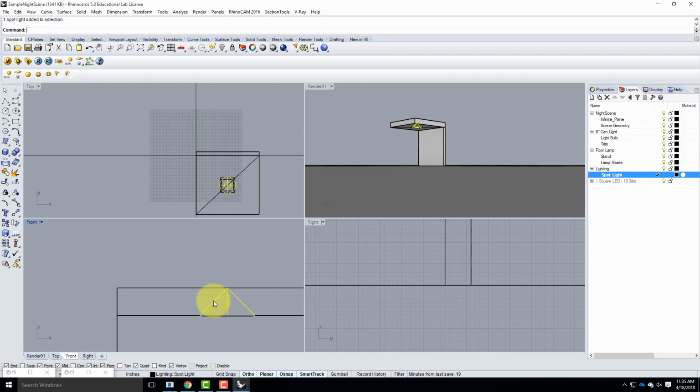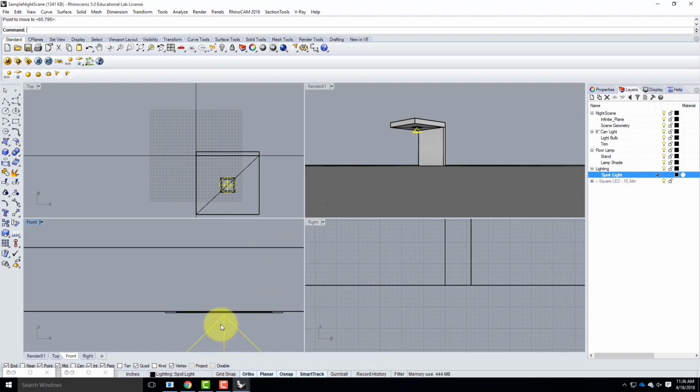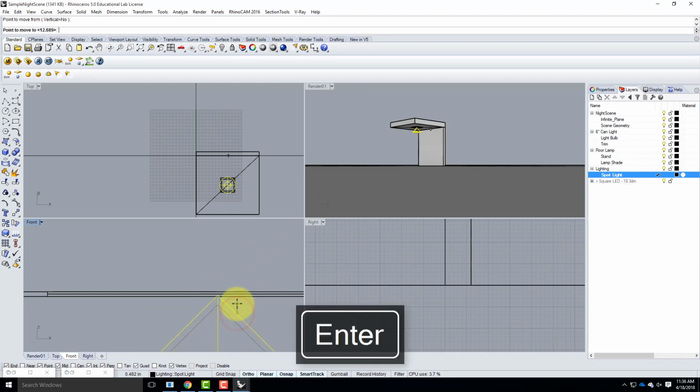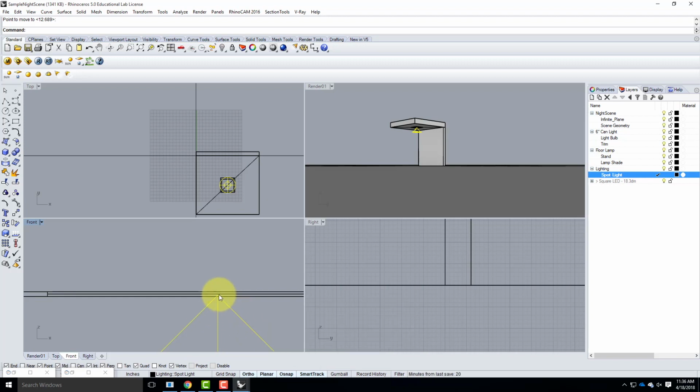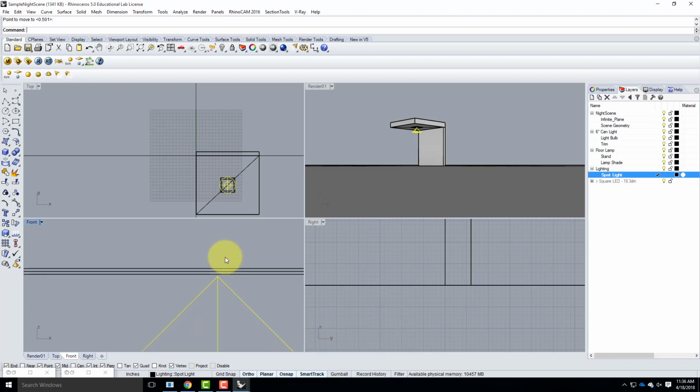When I create this light, however, I have to make sure that the whole light is not contained within any other objects. So right now, this point here is contained inside the wall above, so it's not going to shine on anything. So I need to move it down such that the whole light is below my light. You have to be really careful. Don't accidentally do this, where that tip is just barely inside your geometry. Make sure it's actually out. So move it down just a little bit. There it is. So we've got a little bit of a gap there.